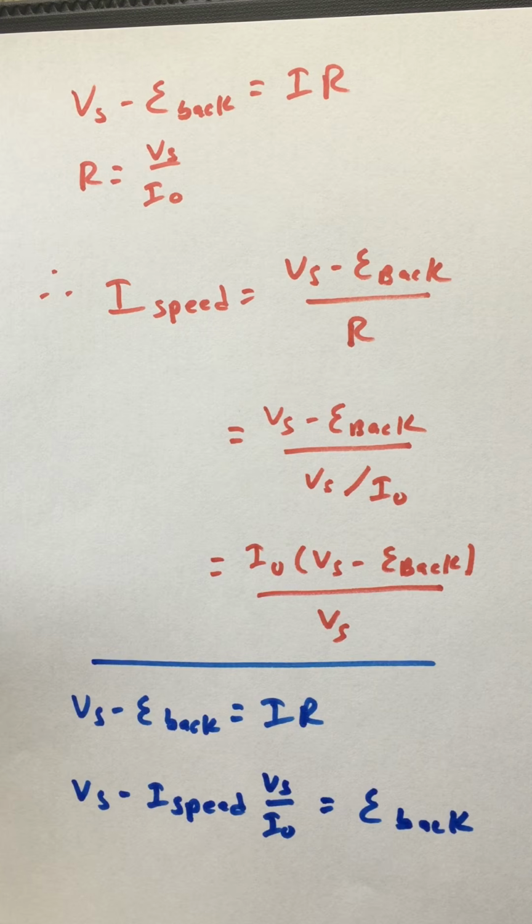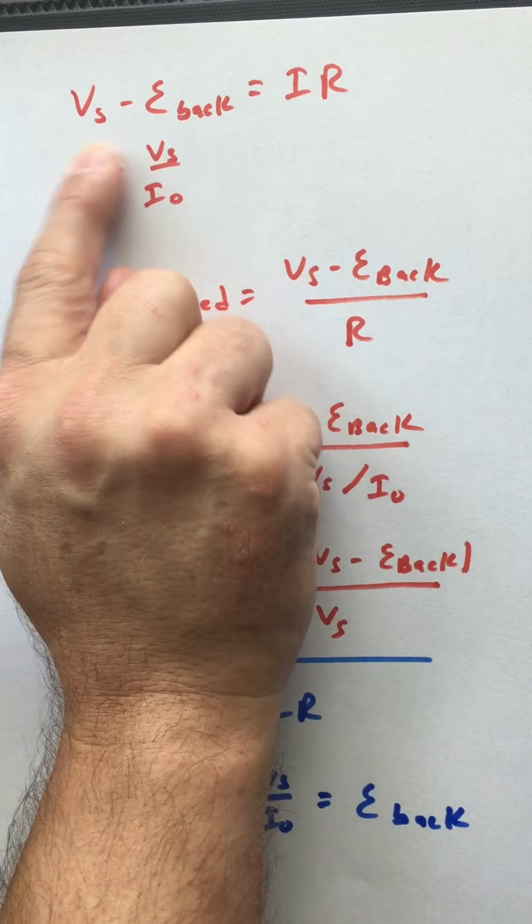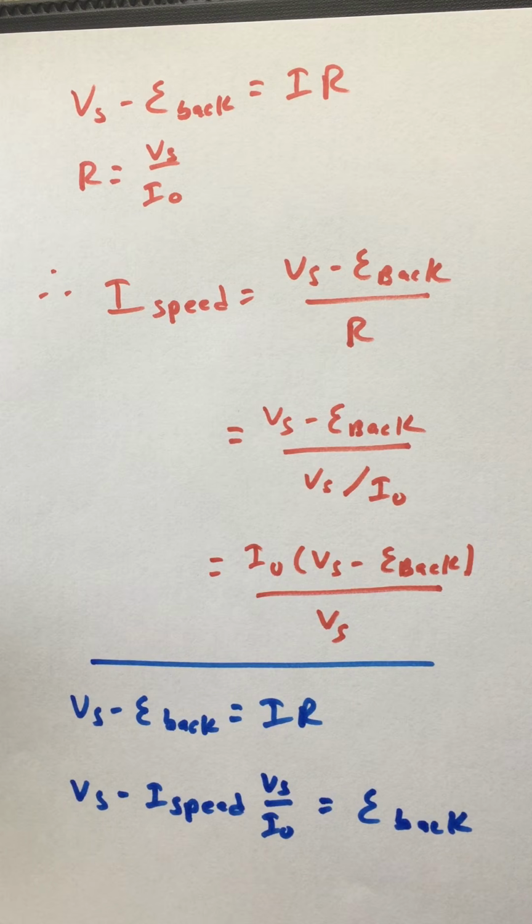Ohm's law is actually a simple equation. The only thing we've done to it is we've added this other term to determine the total voltage. But after that, it's still just as simple as it was when we were using it to solve circuit problems. It's just in this case, we have this other component, and you just have to know that the maximum back voltage occurs when this thing is at speed. Before it starts spinning, the back voltage is 0, and it varies in between there.